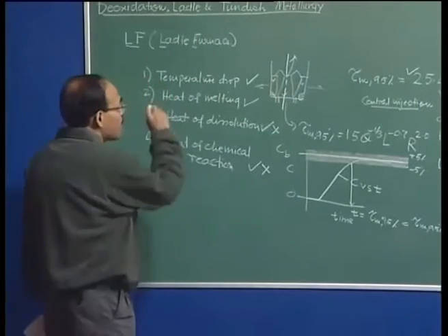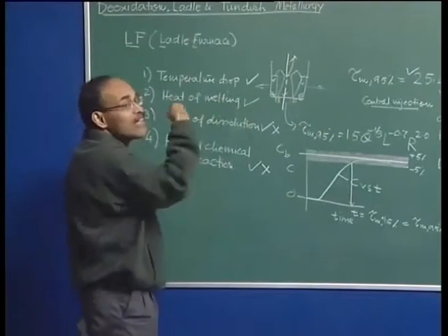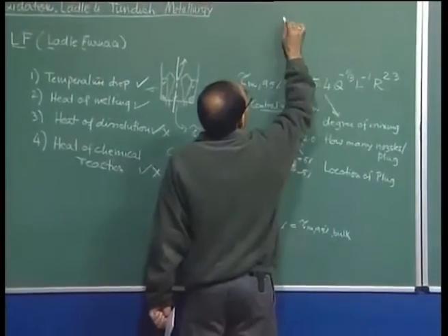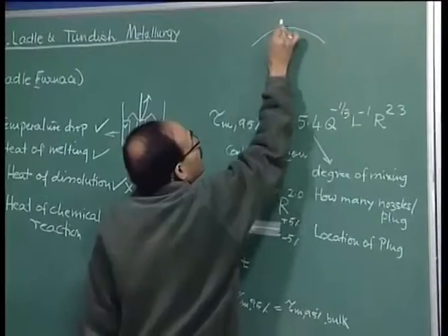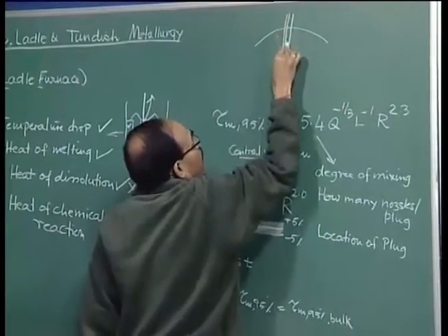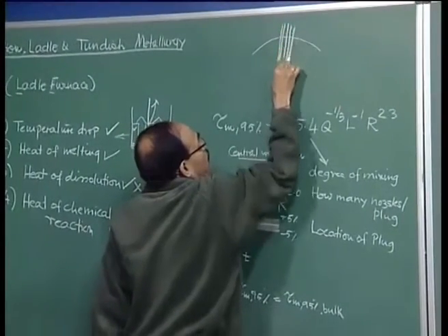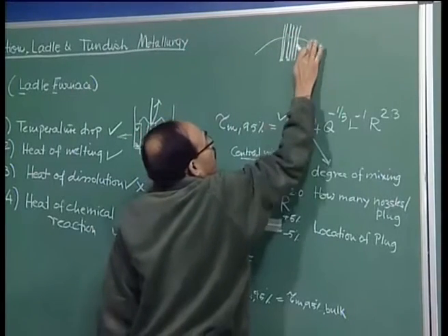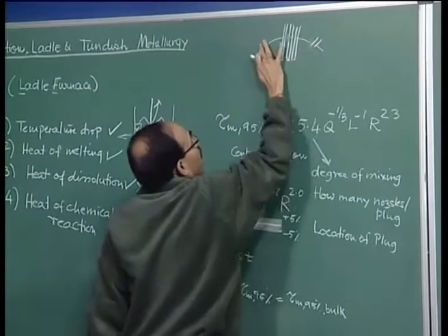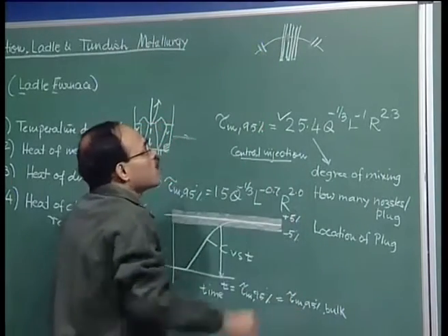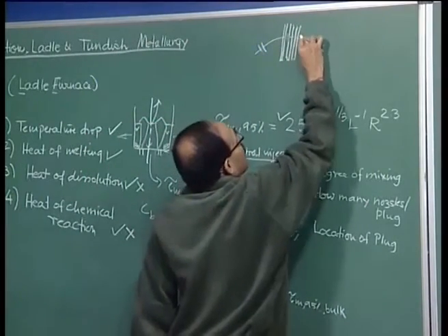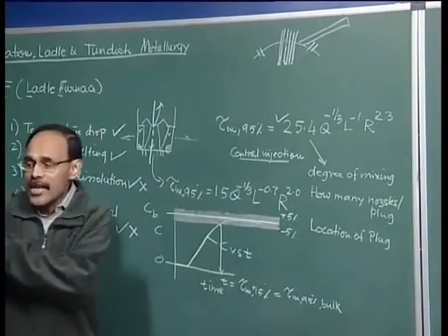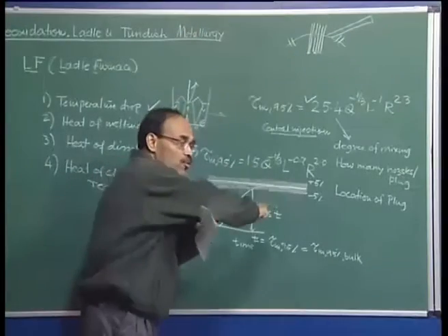Now, how does a ladle furnace look like? This ladle is converted into a ladle furnace merely by having a roof through which we have an arrangement like electrodes. So, these are my 3 electrodes, and we have a roof here. The entire thing can be attached to an assembly, and it goes like this. The roof is on this particular arm, and the roof can be rotated.